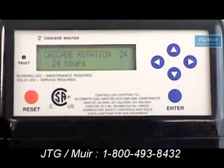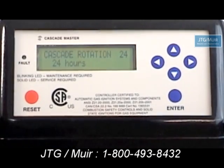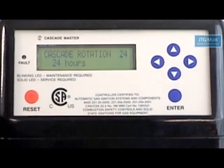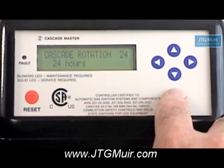The master might start up the first time. The next time after 24 hours the next one will start. And they'll lead, lag, and stage after that. The ultimate goal is that all the boilers have the same amount of runtime and all share the load accordingly.